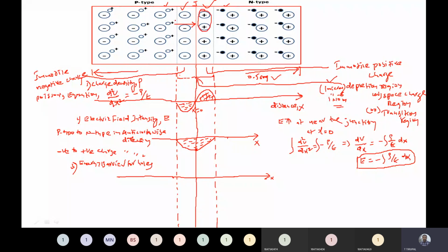This positive charge repels the positive charge hole, and therefore it moves back to its original position. So if this hole wants to cross this junction, what energy should it require? It should overcome this complete energy present near the junction or depletion region.